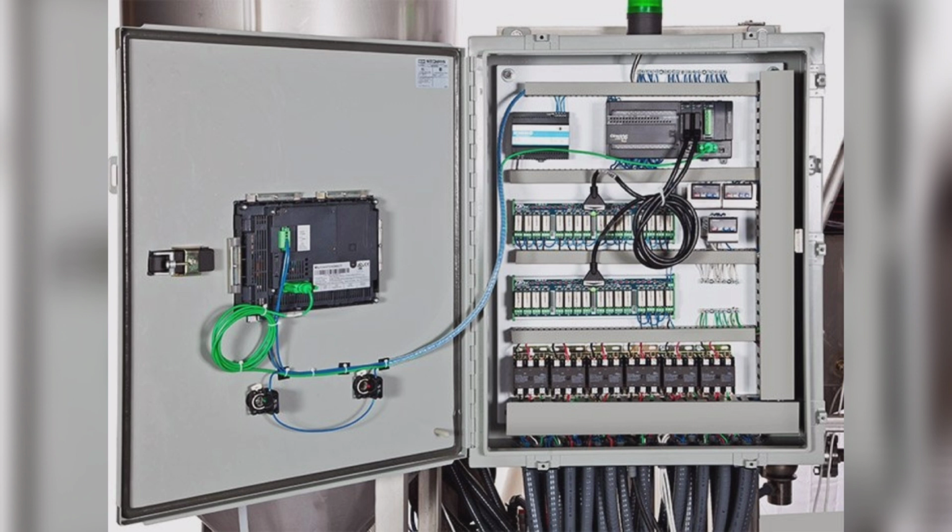Speaking of the terminal blocks, we will have wires running from them to the inputs and outputs. This will allow for the actual control of these assembly lines. Field devices such as proximity switches, photo eyes, and various sensors on the assembly line give the feedback needed to the PLC to control the operation of the line.